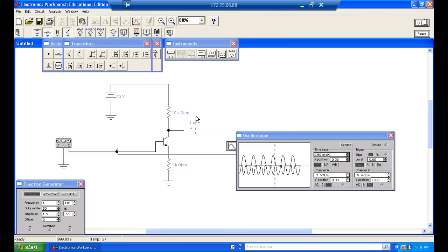But the problem is that it's got a fairly moderate input impedance and a really high output impedance, which means even though we get a power gain, it's not a really big power gain. A common collector doesn't give us a voltage gain, but it gives us a really high current. And then we have a common base, which gives us a voltage gain but doesn't give us a current gain. So then we get the classes of amplifiers. Then we have Class A.